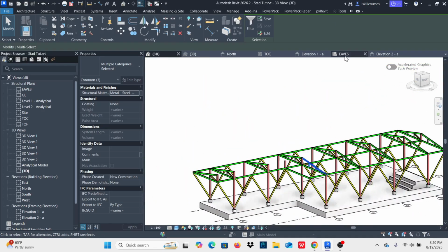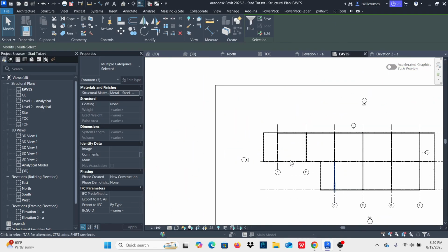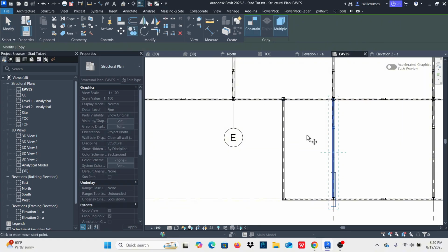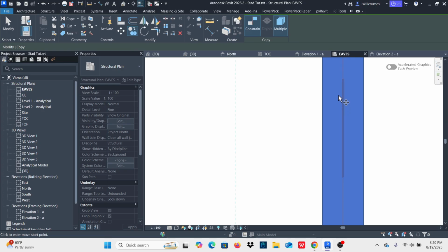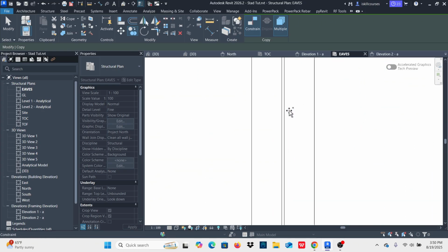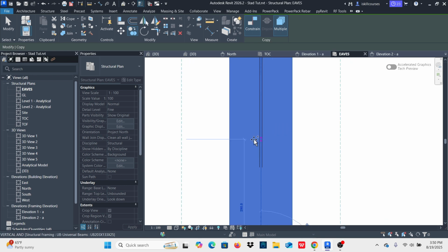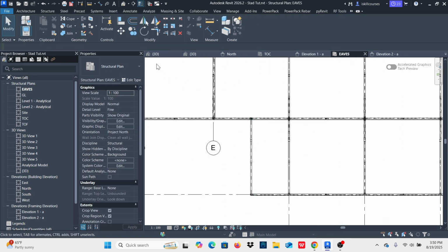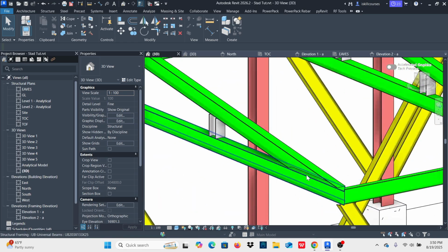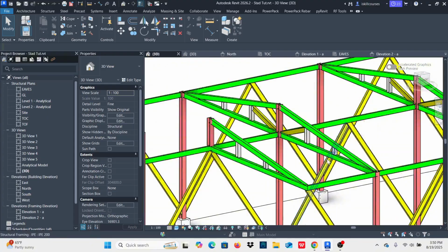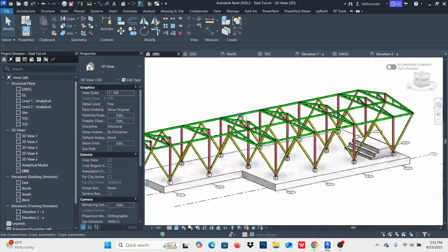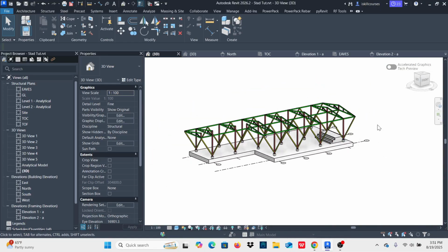Now I'll go to my eaves there. I know that this one is sitting right here and it has to come here. So I'll simply click on copy. Make sure that you pick the middle part. I'll pick that line in the middle, the center, and now come here and zoom in until the center highlights. Okay, so we are good. No errors whatsoever, and it cuts there, picking everything from there. Okay, we can miter here if we want, but I think because of time, we are good.